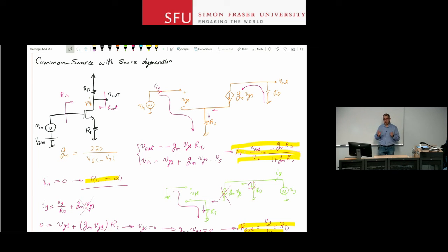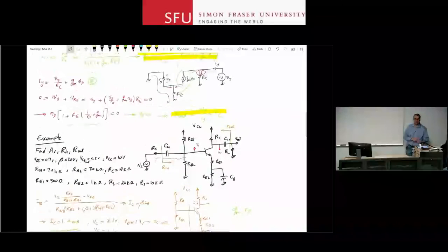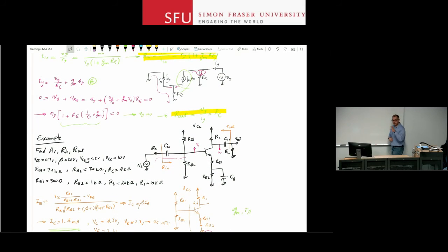You need to have that much practice in order to feel comfortable with it. But from time to time, I show you a circuit that you can reduce to something that you've analyzed before, right? So in this case, this common emitter stage, we looked at it closely. We noticed that everything after RB1 and RB2 and before RL, we analyzed before. We know what that portion in between does. It has an input resistance, output resistance, and a gain.